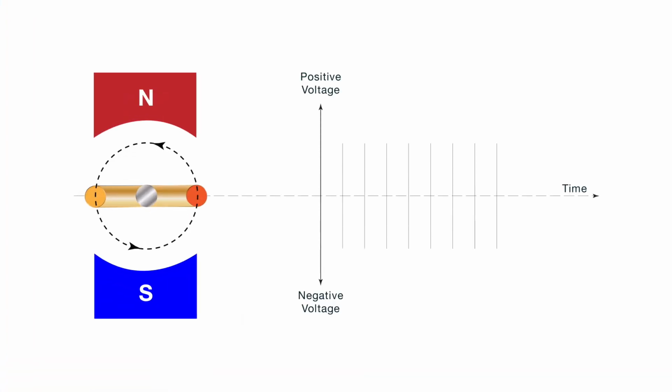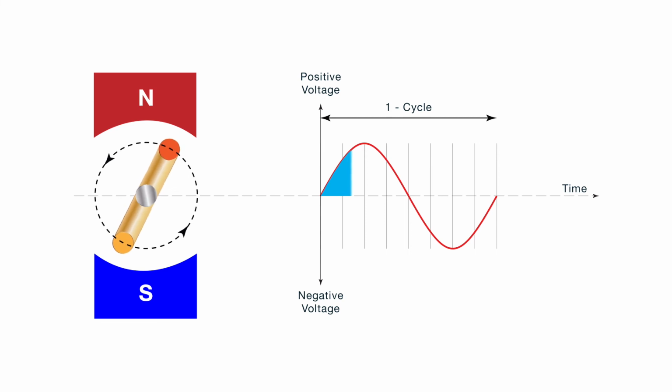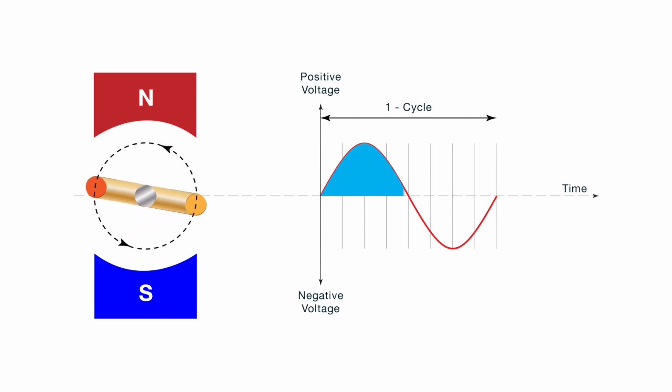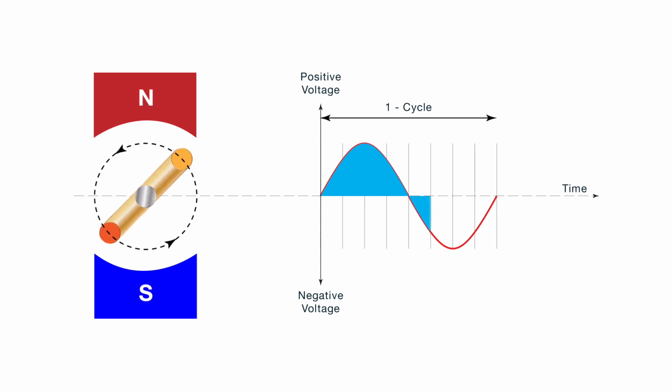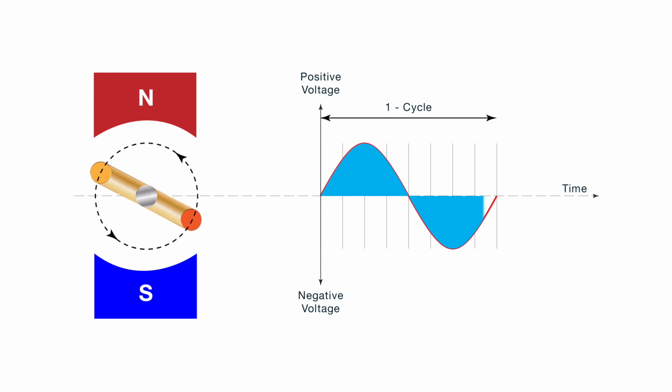Alternating current, AC, is an electric current that reverses in direction between negative and positive, as opposed to direct current, DC, that flows in one direction, which in one cycle represents a generator rotor turning through 360 degrees, as a conductor rotates and cuts across lines of magnetic force between the north and south poles of a magnet. Per Faraday's law, an electromotive force, or EMF, is induced into the wire as it cuts through a magnetic field. The amount of EMF induced into the wire varies on the angle that it cuts through the magnetic force.